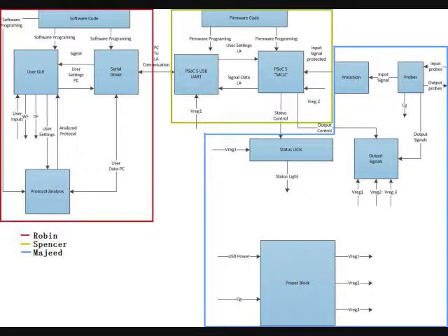The GUI is what the user will see and where they can input settings like how many samples to take. This is also where the waveforms will be displayed. The users will be able to save data waveforms and also be able to open previous data waveforms. The serial driver is the software portion that communicates with the PSOC over USB. The protocol analysis will decode our data protocols, which will be in UART.